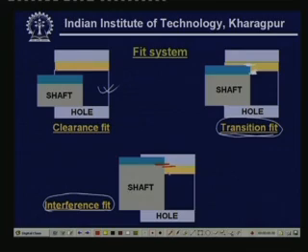Even if we go to the maximum size of the hole or minimum size of the shaft, there is always an overlapping in the basic sizes. So, that is what we call an interference fit. This interference fit could be also from a pressure fit to a tight fit.